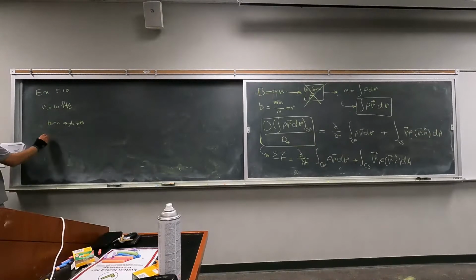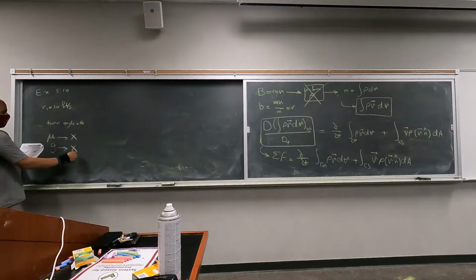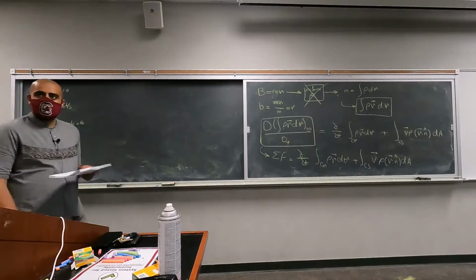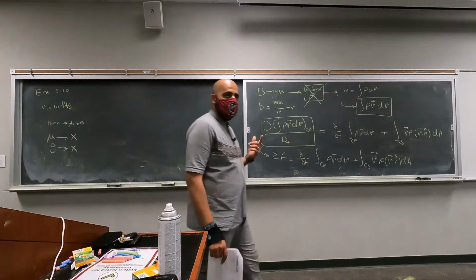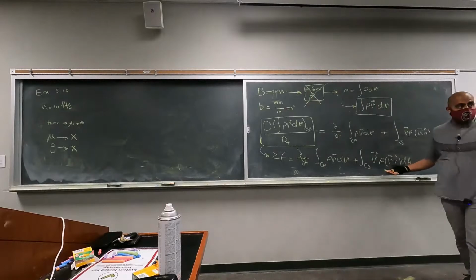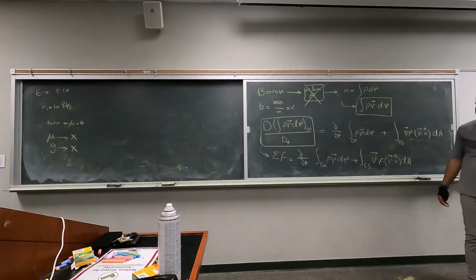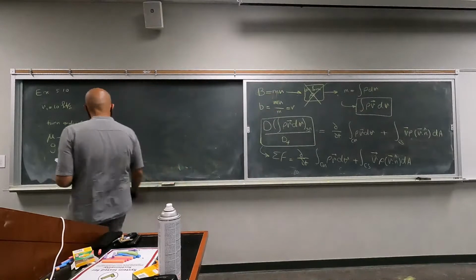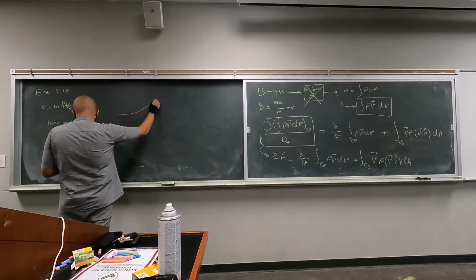So viscous effects, we are going to neglect them. Gravitational forces are also neglected. We want to find the anchoring force. So we are told to find a force. What is the equation we have that will help us find the force based on velocity, or linear momentum? The momentum equation.